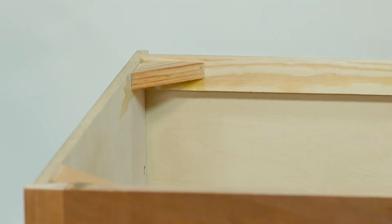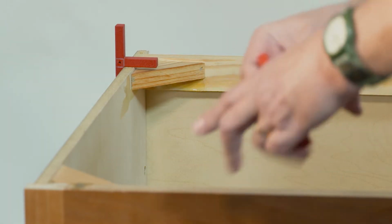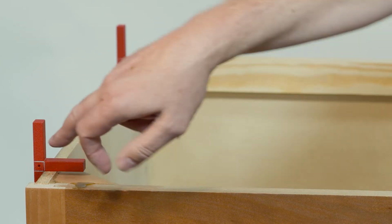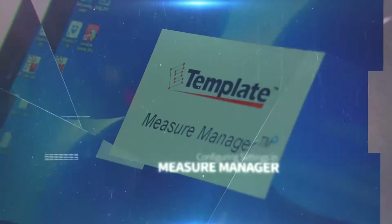So over on this side, we've got bare cabinets. We're going to go ahead and place the markers right on that cabinet. Again, we place two markers per edge, and now we've got this front face that we can hit, which is in line with the cabinet, or we can hit that silver scribe line. Either way, we're good to go.